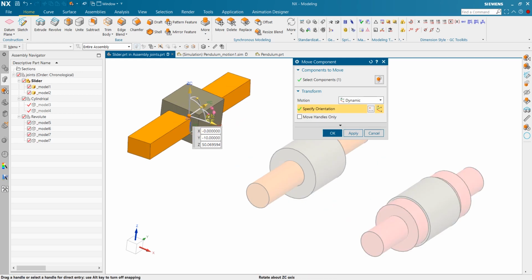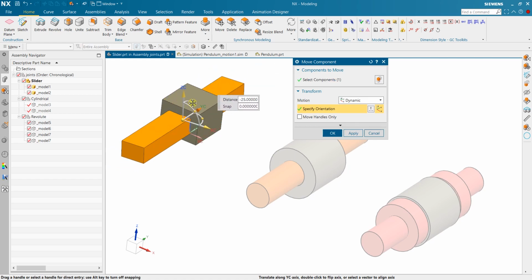So the joint won't allow any kind of movement except this type. Any kind of movement other than this, it will generate reaction force inside the joint, and it will affect the friction force inside the joint. So this is a slider, and I will come back to explain the friction on this type of joint later.